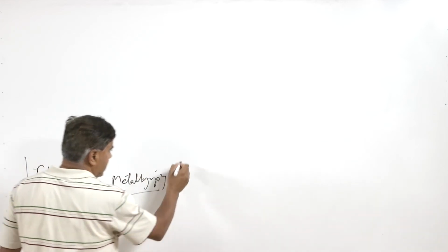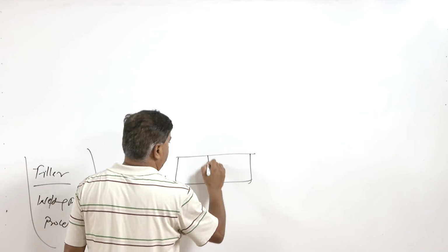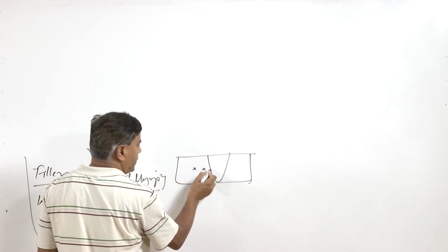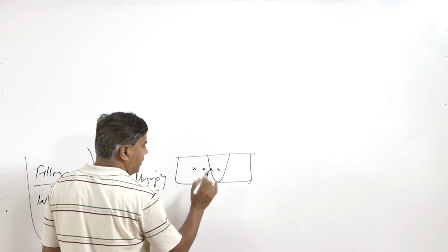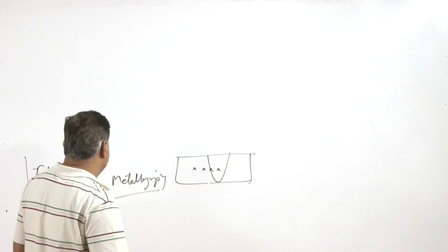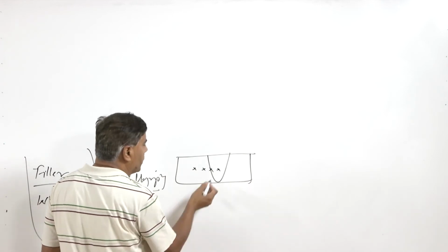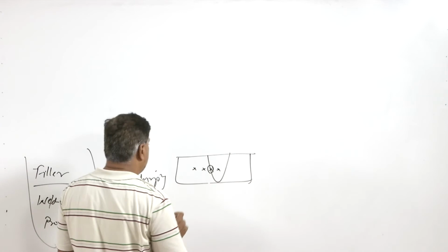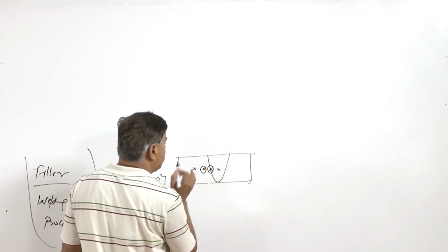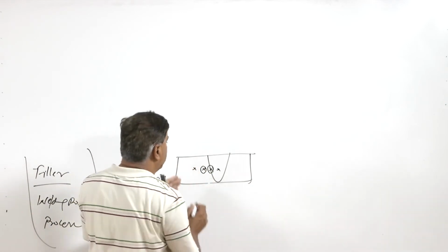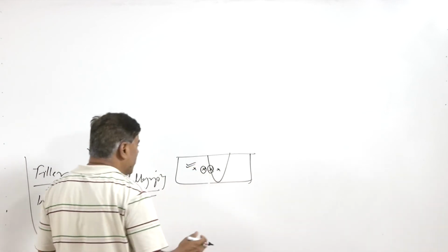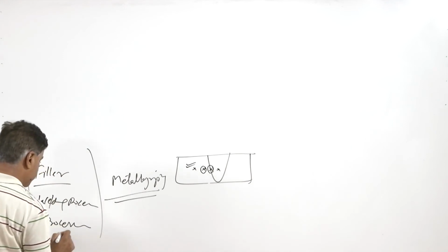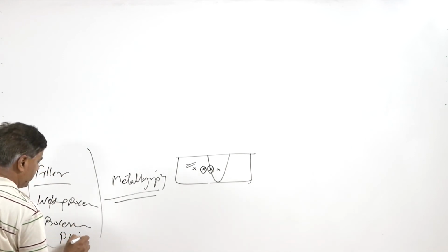So, say this is the weld joint, and if we do the metallography, we can have the microstructure of the base, heat affected zone, of the fusion boundary, and also of the weld center. So, these will help us to indicate whether the penetration has been proper or not at the fusion boundary, or whether the kind of phases being formed at the heat affected zone and the base metal are as per expectation, or it is something else, or if in the procedural aspects there is a PWHT.